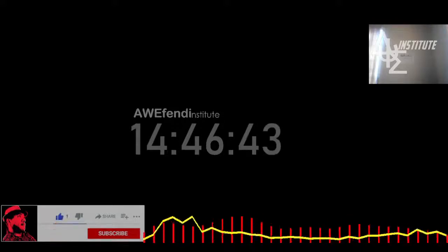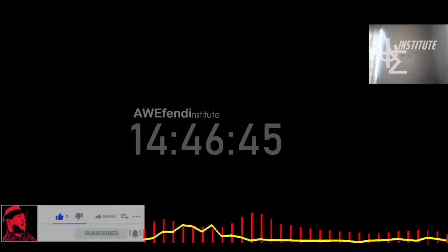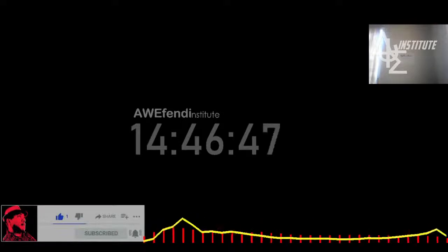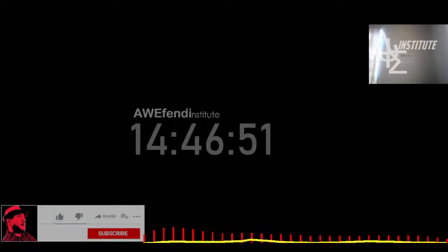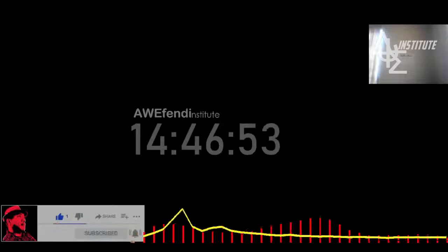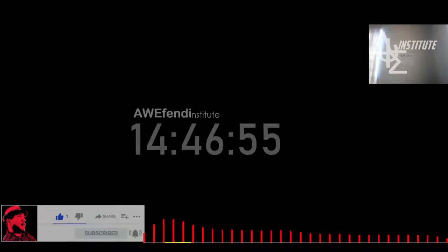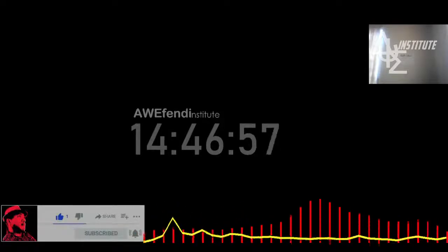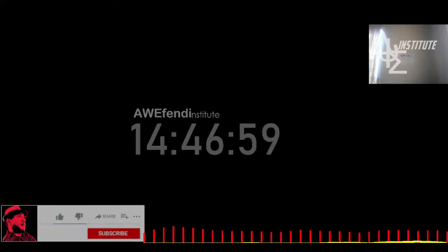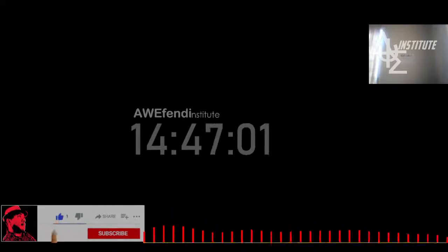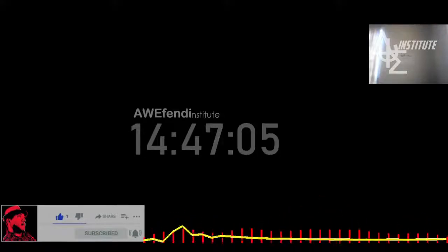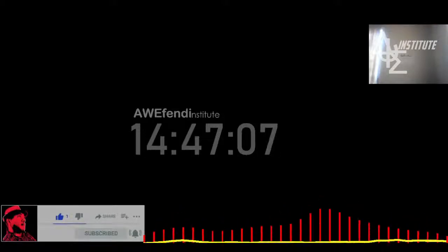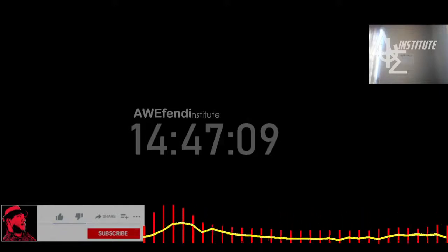But another thing that we wanted to do, we wanted to check what was the heat flow on the faces and compare it to an analytical solution. Now, to do this, we can use the monitor feature that Madhu was showing, and we can create a custom monitor. So we're going to click on monitors, custom, and then select the variables that we want to look at, in this case, heat flow, and the surface from which we want to get heat flow. In this case, from one of the faces, and we can see that we get a value of minus